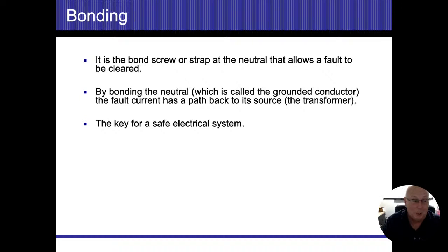Because there's going to be a time when, if the house gets foreclosed and the water meter gets removed, we don't want the person who's going to be connecting it together to touch one side that's going to be 0, then touch the water main that might be something different. Once they touch those two different objects, if they're at different potentials, then that electricity is going to flow through them before they put it together. So we need to have a jumper cable that's loose, connected. When I say loose, I mean the wires aren't wrapped around it really tight. The connections are tight and secure. We should actually be moving those to make sure that they're tight so that I know I have a good connection between both sides of my jumper cable. All right.